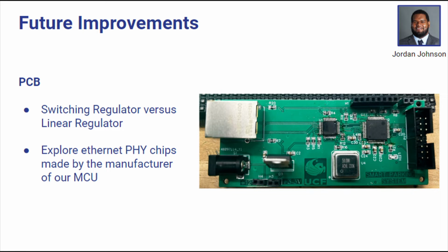In our initial design, we had a 12-volt input into our PCB, and even though our design does not pull a lot of current and does not require something that is super efficient, our regulator would still get pretty hot since this 12 volts is getting dropped to 3.3 volts. This led to us changing our voltage input to a 5-volt input to counteract the heat that was let off by the regulator, which really caused us to spend more money on our design.